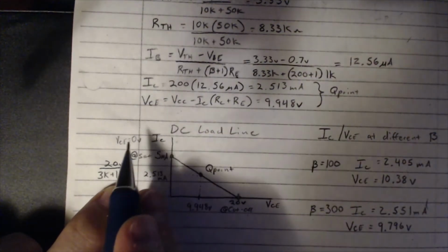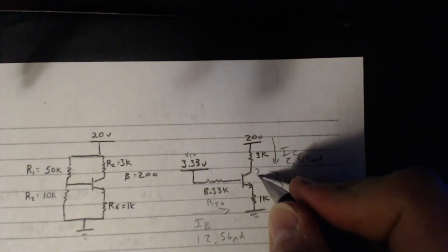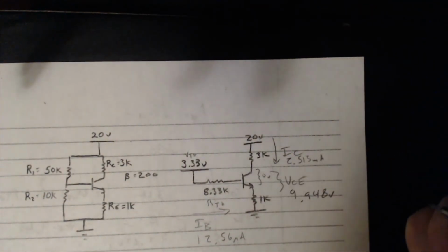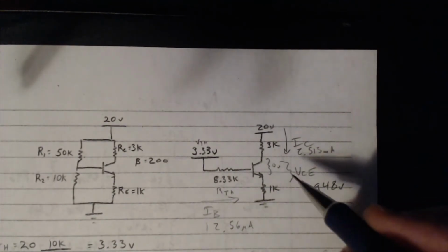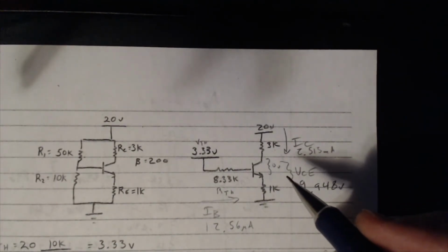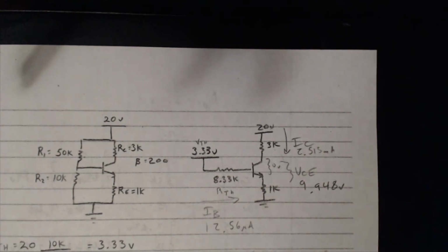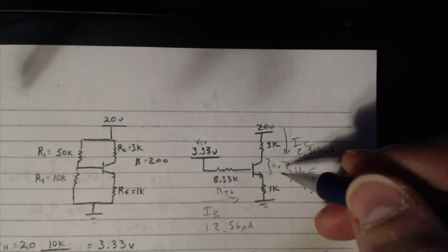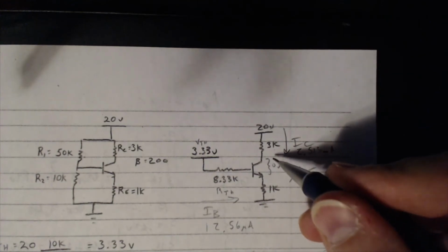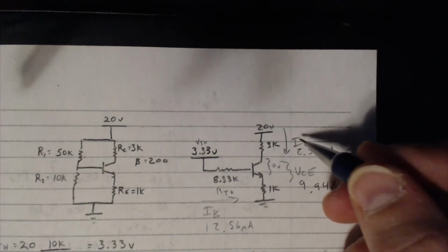This is just 0 volts between the collector and emitter over here. So we're assuming 0 volts here. Okay, so essentially as saturated as this transistor could possibly ever get, behaving like a perfect or ideal closed switch.